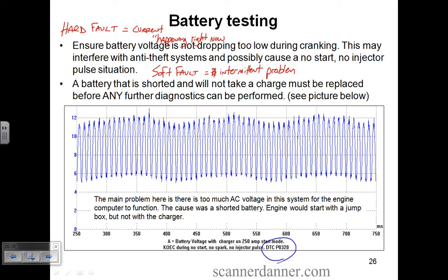But ultimately, what we're looking at was what I saw. Let's see, this is a Ford, so Fords use, okay, that would make sense why I didn't see it. Fords use crank sensors that produce AC sine waves. It's a 2-wire sensor. We'll talk more about this in section 21, I believe, ignition system inputs.